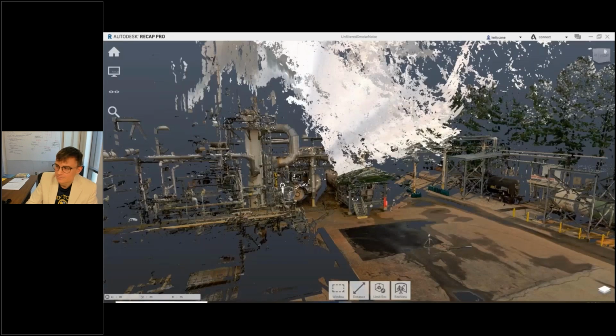Environmental noise happens with steam, dust, snow, rain. Scanners have filters that eliminate this internally, but for the stuff that the filters miss, you'll just have to go in and manually clip and clean it.